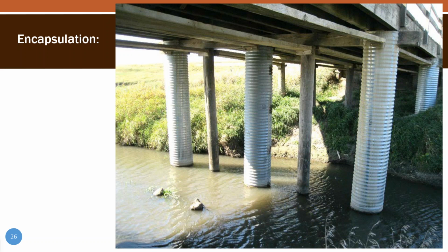through the member. If I have splits that's like right through the middle height of the member, I'm starting to get worried that that's being load induced, because that's the highest kind of shear loading that it will see, and it'll start to actually split your member apart. If I have a check in a pile, it doesn't really get me very excited. Even a split in a pile, I would want to see where the split came from, but it may not get me as excited either because of how the load gets distributed in them.